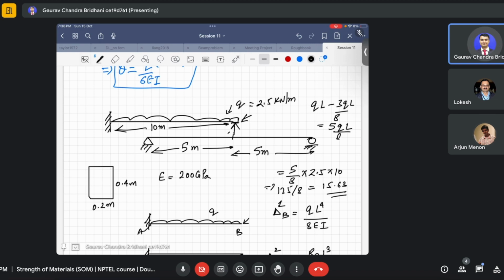Yeah, because in most of these structures deflection plays a more important role. Whenever we design for strength, most of the time we design it with over-strength. So if a support is carrying some 15.53 kilonewton of load, and that changes to 15.59 or 15.9, it will still take that load. Even 16.9 it will take, because most of the time we design higher for strength, but deflection is more important to handle.